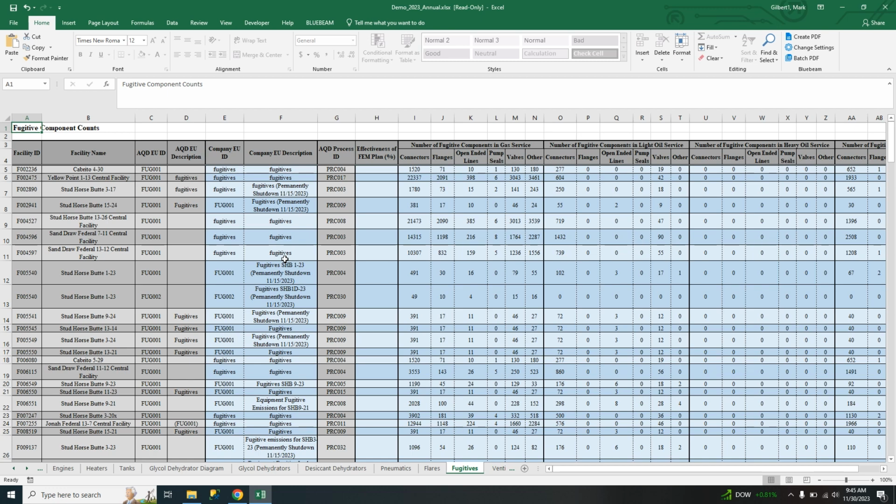If there is a fugitive emission monitoring or FEM plan, add an effective control efficiency under column H. When calculating best available control technology or BACT, the New Source Review, or NSR, uses a 50% effective control efficiency for semi-annual instrument-based monitoring and repairs, and a 60% effective control efficiency for quarterly instrument-based monitoring and repair. If a different control efficiency is used, the methodology to quantify emissions and emission reductions must be approved by the division. Portable analyzers do not qualify as instrument-based monitoring.